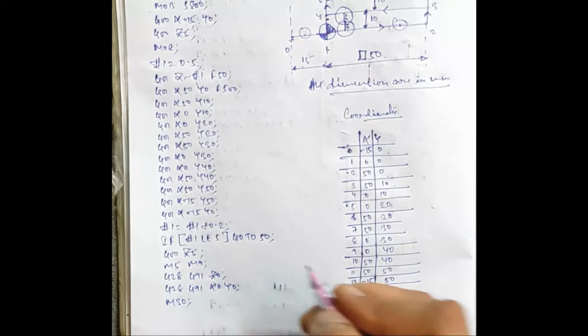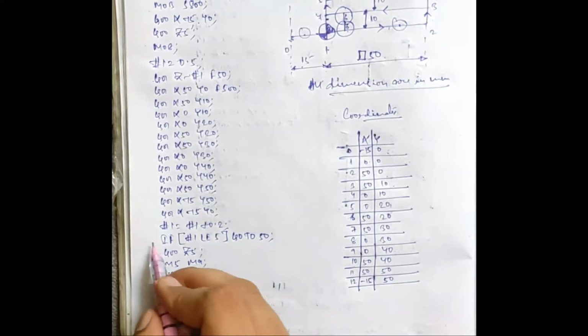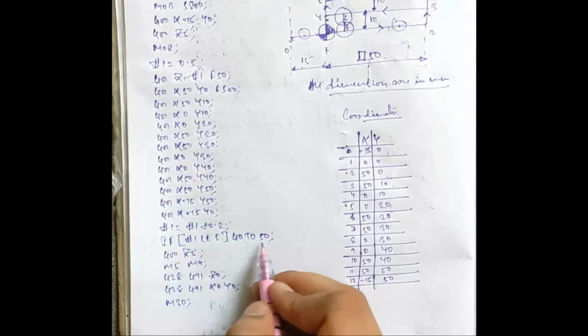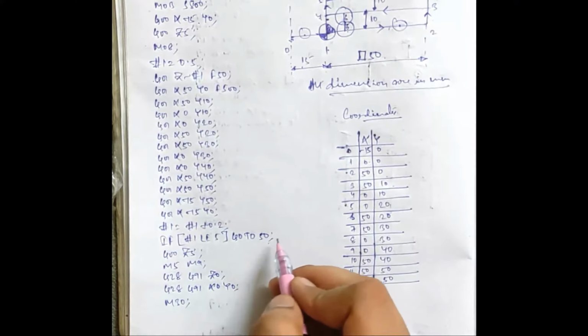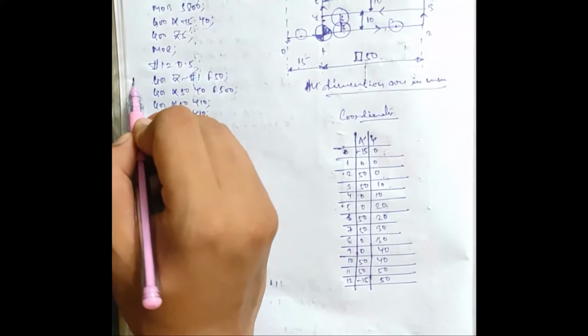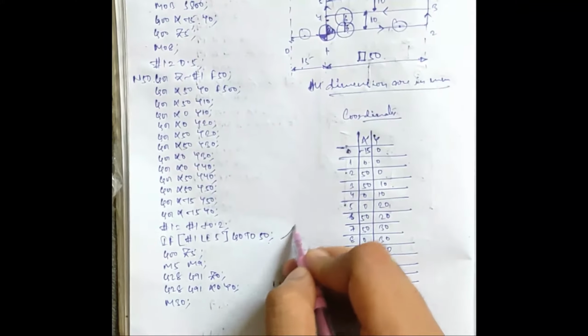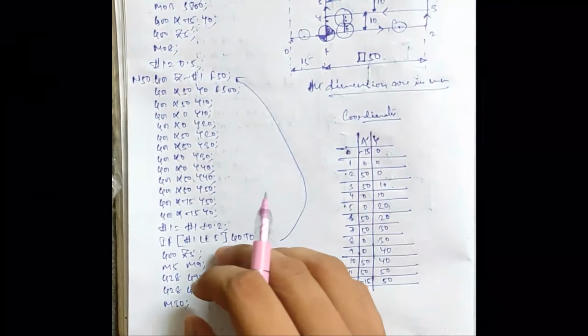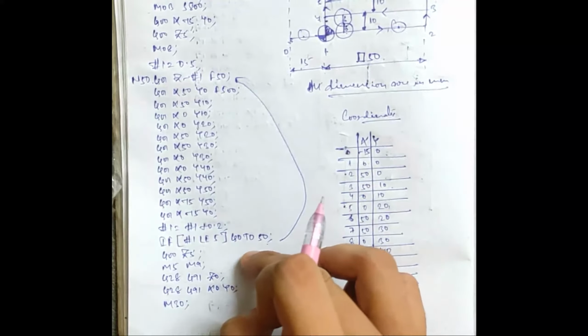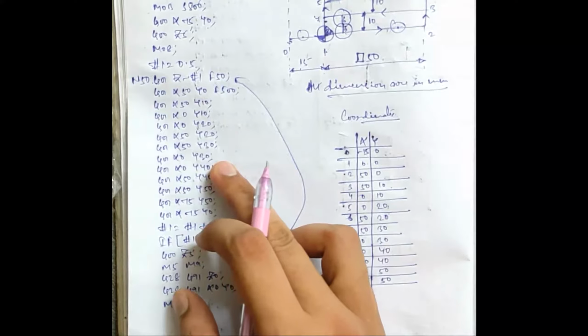Okay. So this block is saying something over here. GOTO 50 means you are commanding this line to go to block number 50. Okay. So block number 50 is over here, N50. It will move from here to here. It will repeat this program, repeat these coordinates, until it gets the 5 mm of material removed.